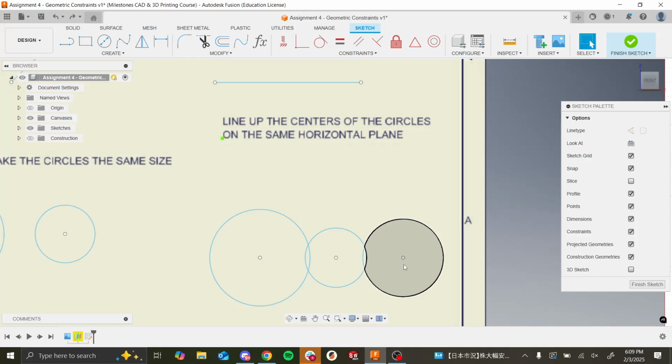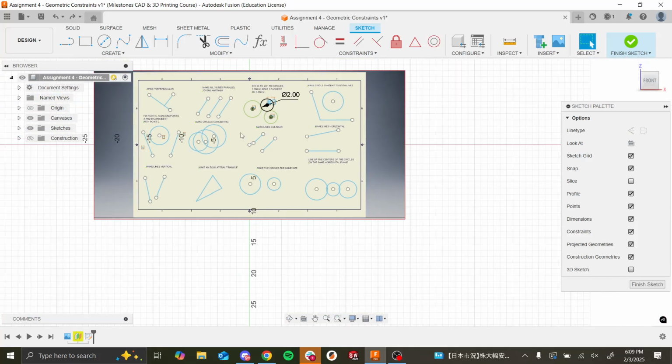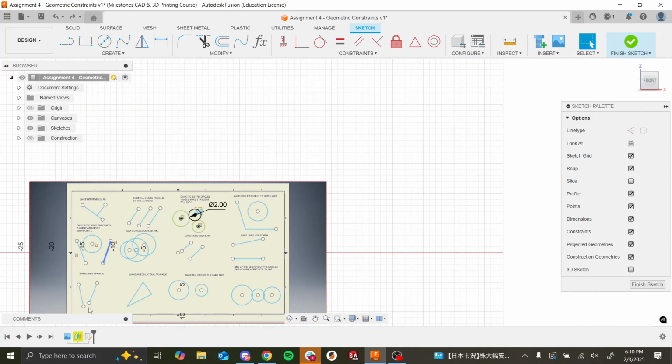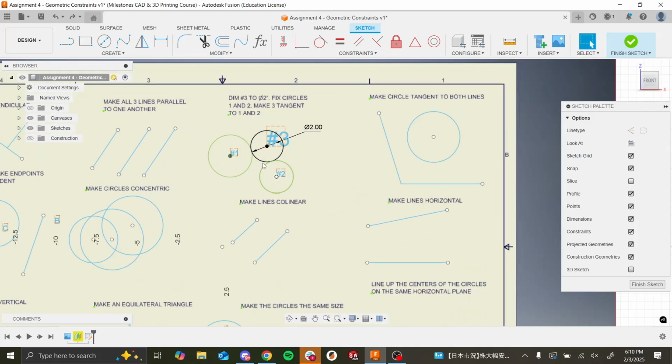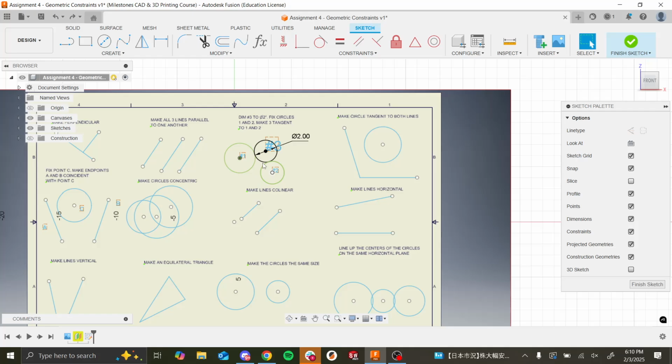Oh, like delete a constraint? I forget. There's some shortcut that allows you to see some of the constraints. I kind of forgot it. But a lot of the times I just delete something and redraw it, because I find that to be faster, especially when you have a lot of constraints. Sometimes one of the constraints will cause something to break. So I usually just start from a fresh canvas and then I'll delete an arc or something and redraw it. Yeah.